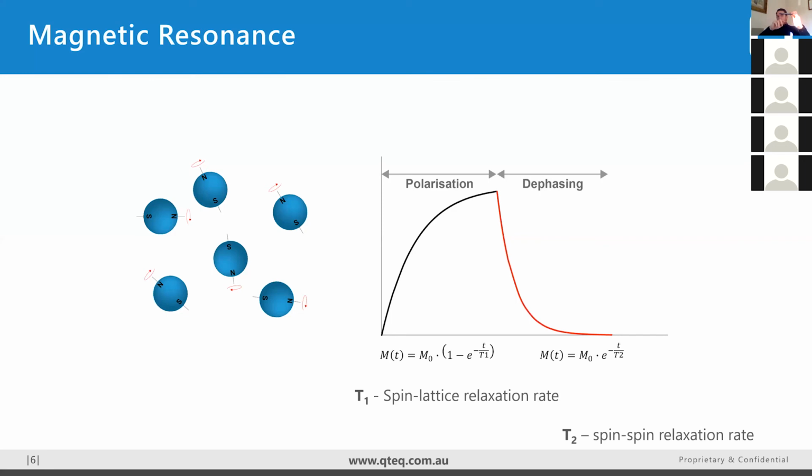So in a layered formation, if you take the arithmetic mean, you get your horizontal hydraulic conductivity, and you can just average the values up in your zone of interest. And if you take the harmonic mean, you get the average vertical hydraulic conductivity. If the formation is very anisotropic, so very random, then you just use the geometric mean, and that is the same for horizontal and vertical hydraulic conductivities.